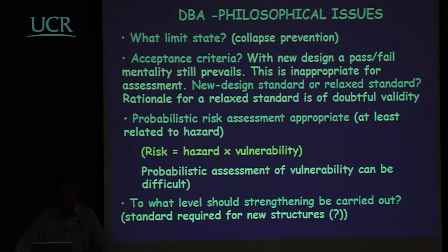With new design, we have basically a pass-fail mentality, which still prevails in our design, despite the fact that we use probabilistic seismic hazard assessment. This is inappropriate for assessment. New design standards or relaxed standards, which should we be using? The rationale for a relaxed standard is of doubtful validity. In other words, if we say that we strengthen the structure to 50% or some other number of the design required for a new strength, unless we know what the risk associated with that is and are prepared to accept that, we should not be doing it.